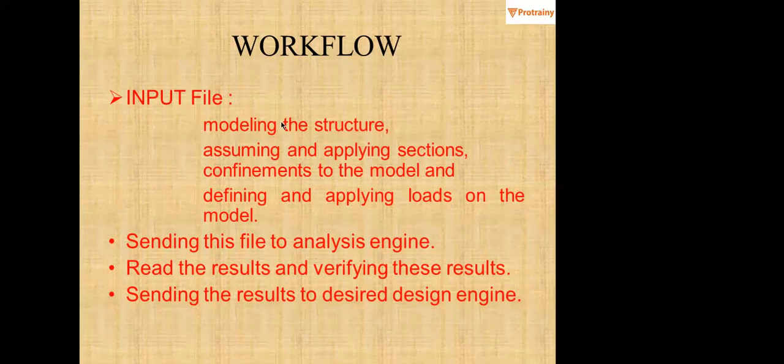So the input file: modeling the structure. You have to make sure that your model in this software is related, as much as possible, to the actual structure on the ground. So modeling the structure, then assuming and applying sections, which are like cross sections. Then comes confinement, I mean restraints to the model, and defining and applying loads on the model. So this all includes the input file.